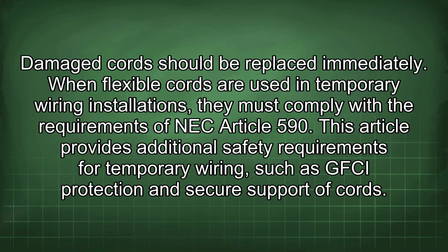When flexible cords are used in temporary wiring installations, they must comply with the requirements of NEC Article 590. This article provides additional safety requirements for temporary wiring, such as GFCI protection and secure support of cords.